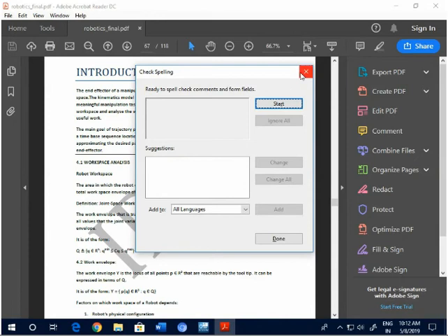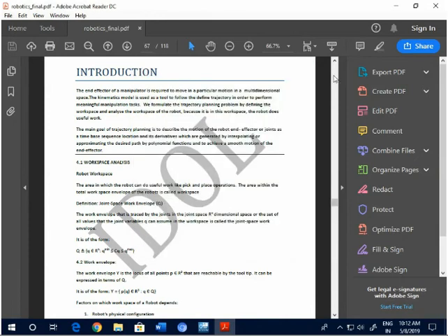In direct kinematics, we find position and orientation of tool and gripper with respect to the base. This was given in your 4x4 composite coordinate homogeneous matrix, and it was also called the arm matrix. And it was given by T raised to tool by the base.